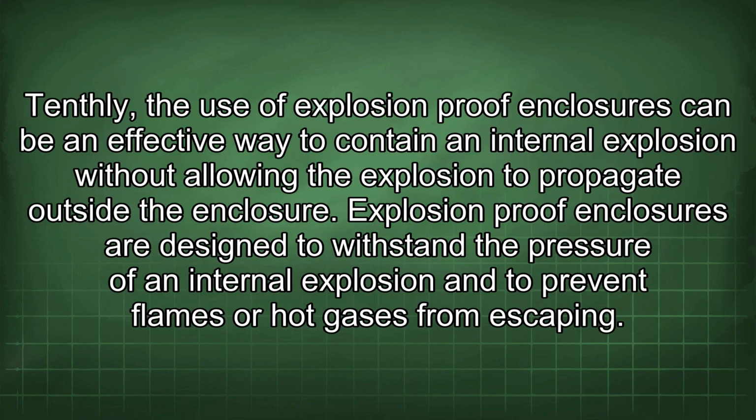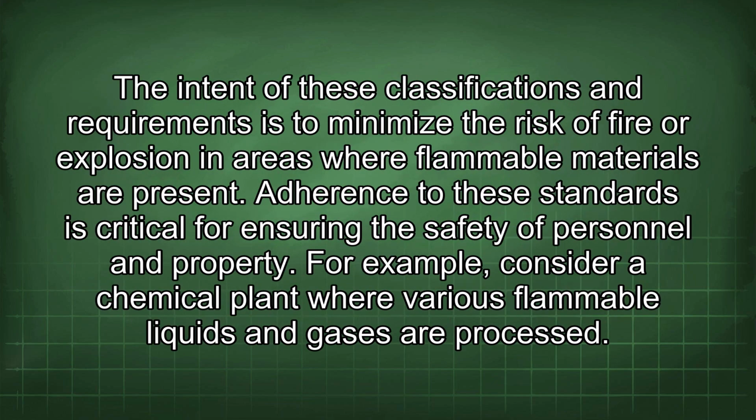Tenthly, the use of explosion-proof enclosures can be an effective way to contain an internal explosion without allowing the explosion to propagate outside the enclosure. Explosion-proof enclosures are designed to withstand the pressure of an internal explosion and to prevent flames or hot gases from escaping. The intent of these classifications and requirements is to minimize the risk of fire or explosion in areas where flammable materials are present. Adherence to these standards is critical for ensuring the safety of personnel and property.